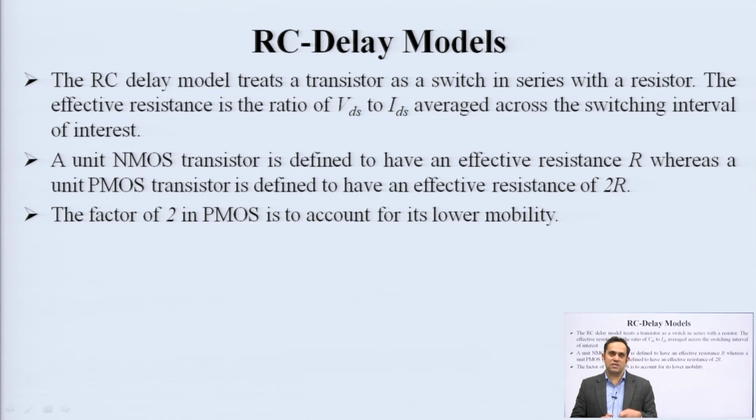And since in a CMOS circuit, a complementary MOS circuit, we want symmetry, we want the PMOS circuit to be analogous or complementary to an NMOS circuit. So, we deliberately model a higher resistance for a PMOS circuit as compared with NMOS, so that we have symmetry: when a signal is rising or falling, it should have equal timing.